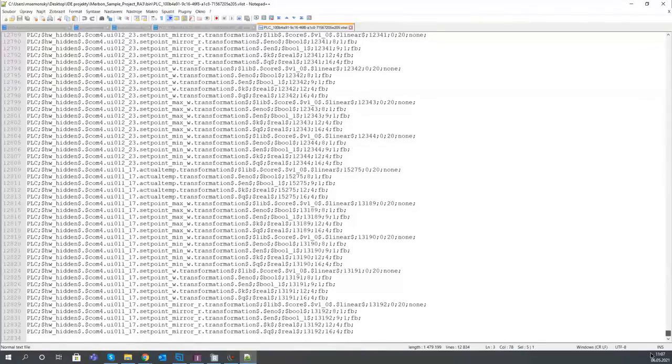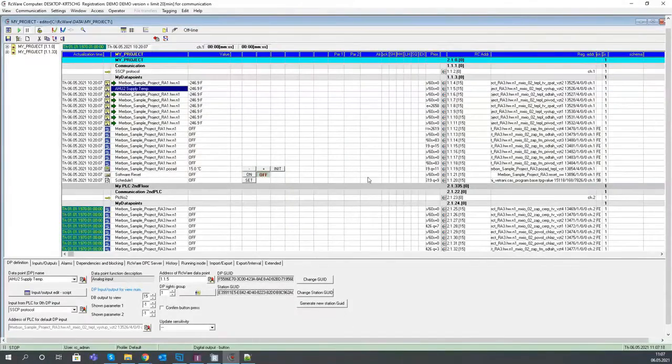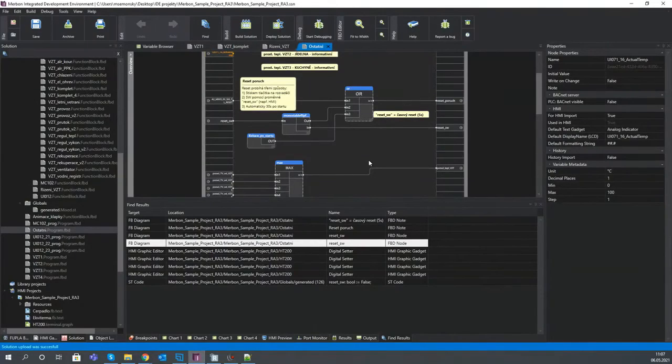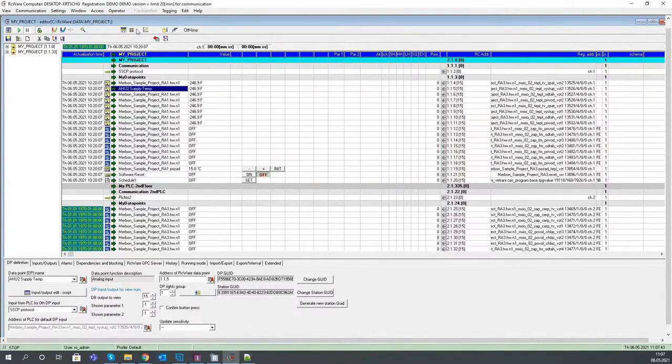And the old variables just keep their COM IDs and you cannot see any difference. But if you make some massive changes, then some of the COM IDs may vary or be different. And this will also spoil the bindings between the SCADA table and this software structure, which is in the PLC. So the structure of the memory may change, but if it influences the data point table here, it can be fixed by tagging all the data points by Control T,